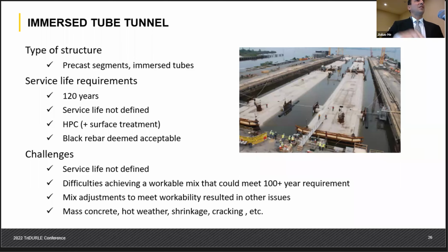What that means is that your mix becomes more difficult. Because if you need to create mixes that are more cracking resistant, all of a sudden they're not that workable, right? And you have all this rebar that the design engineers want. So all of a sudden you have more issues now. How do you make the concrete workable to make sure that you can consolidate it? But because the mix needs to be more difficult since we could not use a corrosion resistant rebar, all of a sudden it becomes a challenge for construction, right? So how do you manage that?